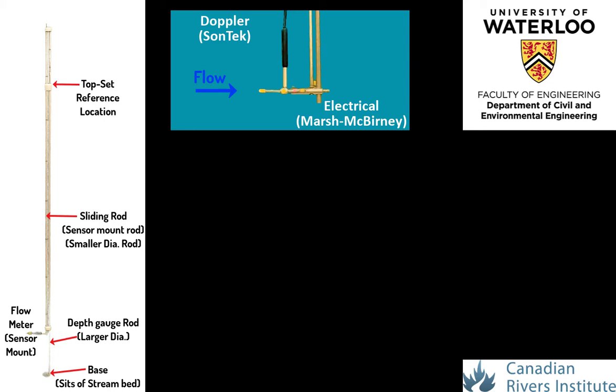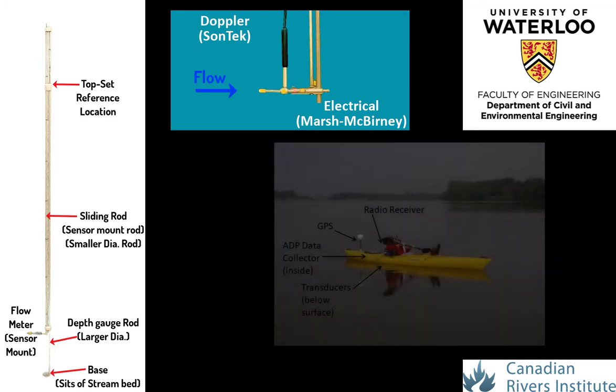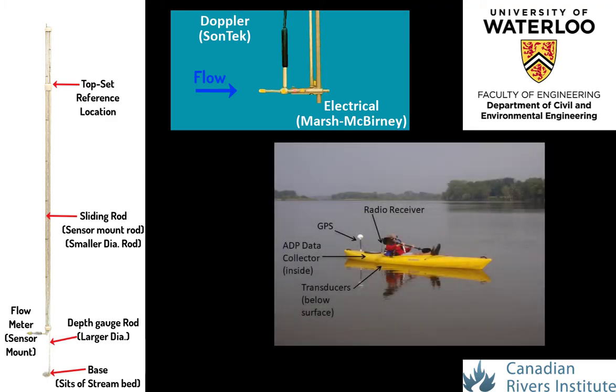Calibration of velocities in a still bucket of water, sampled directly from the watercourse, is always recommended before proceeding with the desired measurements. Doppler-based flow meters do not in fact measure the velocities of the water proper, but rather the suspended particulate matter within the flow field, which is assumed to be moving at the microscale under the same magnitude and direction as the flowing water as it passes the sensor.